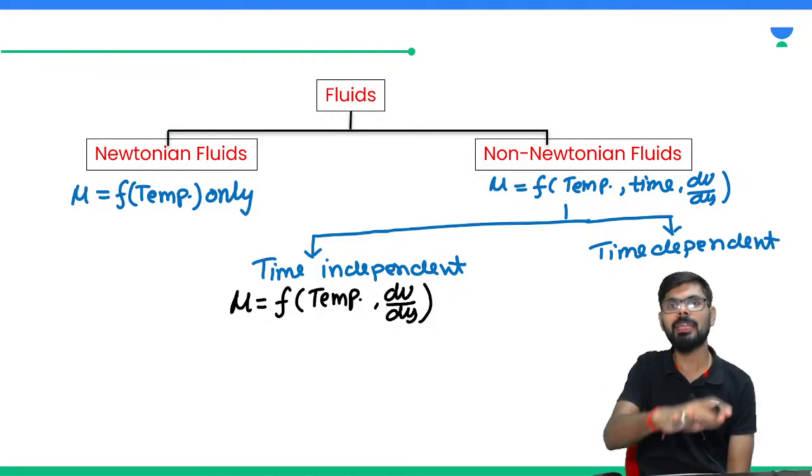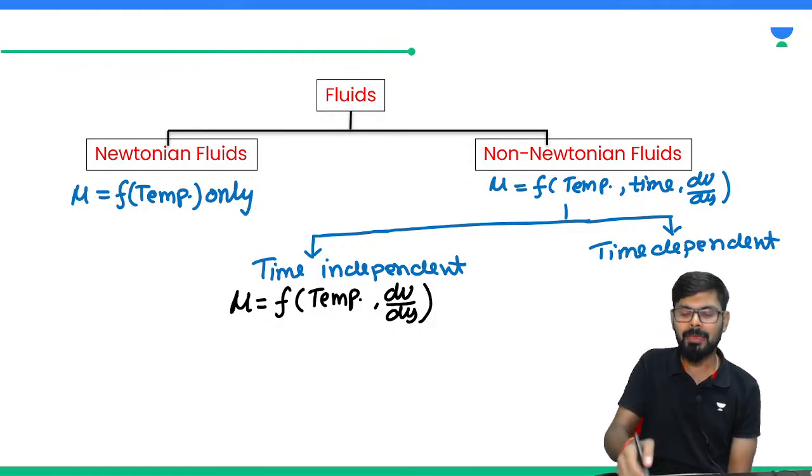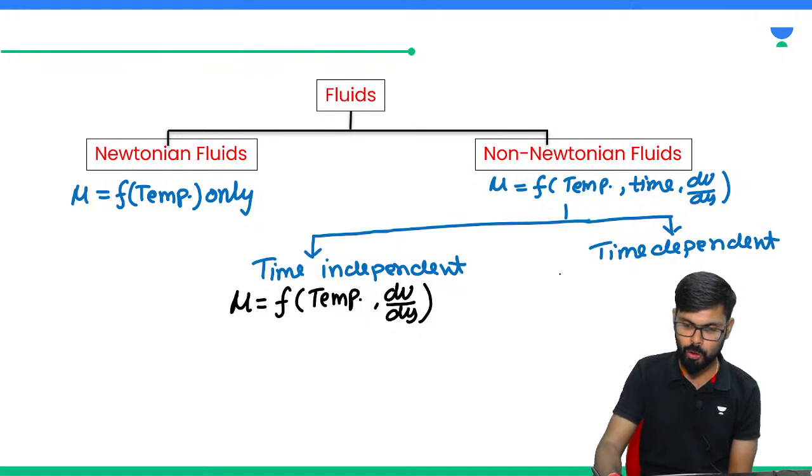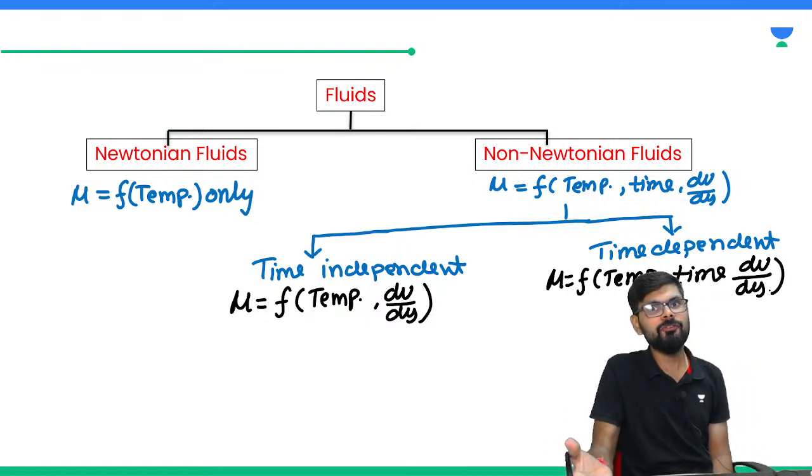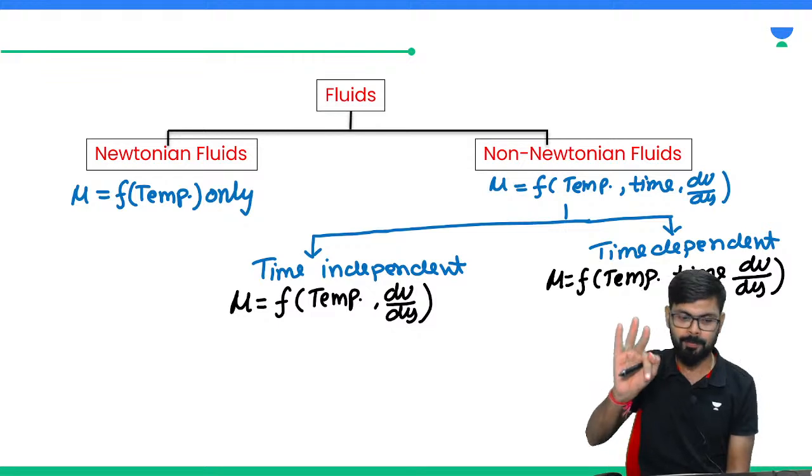It is time independent, so it will not depend upon time. And for time dependent fluids, mu is a function of temperature, time and du by dy. So time dependent fluids depend upon all three.